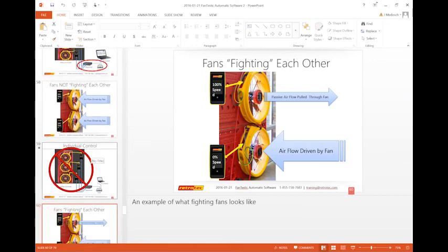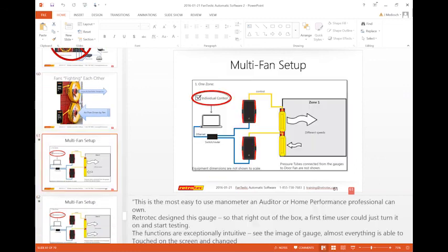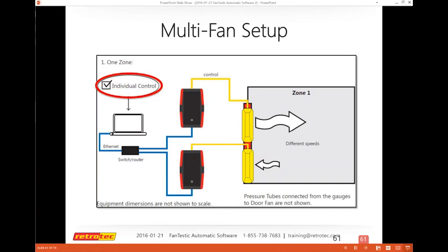So you can either do this in the software, or you can do this by wiring the fans in such a way that they're hardwired together. When you daisy chain fans together, as I think Joe's probably about to tell you, all those fans are common, meaning the same control signal goes to each fan. When one fan increases in speed, they all increase in speed.